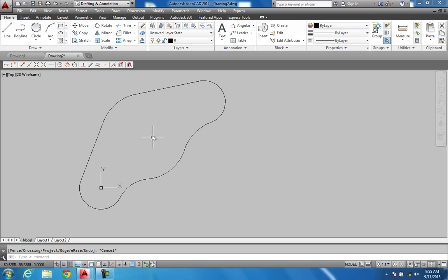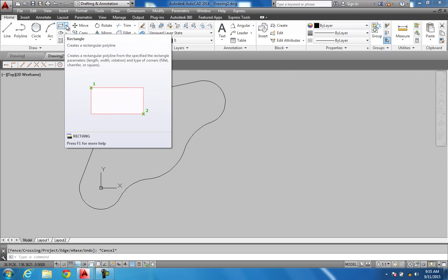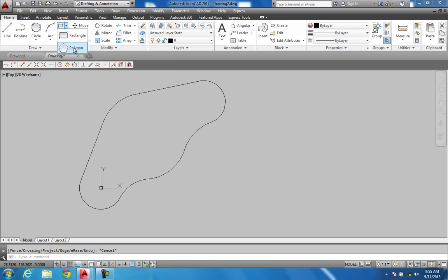So let me get some dimensions on that. We'll start out with this hexagon here in the middle. Now it's asking for a 60 millimeter hexagon. Hexagon has 6 sides, and if you come up here to this point right here, you see a rectangle. If you'll click down and go to polygon, it'll ask you down at your command center, how many sides? Well, hexagon has 6 sides.